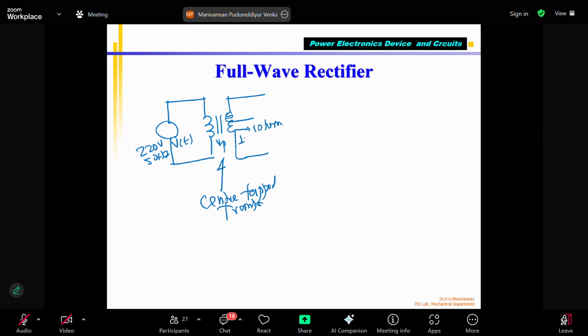This is one end, this is the other end. Between that, there are 10 turns. I will take one more wire from the middle portion. This is 5 turns, this is 5 turns. Say 100 turns, 50 turns. After 50 turns, I tap one more wire and take it out. So this is called a center tapped transformer. On the secondary side, it is center tapped. This is my VS. With respect to this we can say center tap. This wire is called the center tap wire.